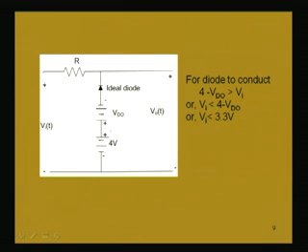So, this diode will conduct current when the voltage at this point is higher than the voltage at the end point. So, the potential at this point P of the diode is how much? From this point, if we see the 4 volt battery, it is minus to plus, so it is positive, and this is again plus to minus, so it is negative.